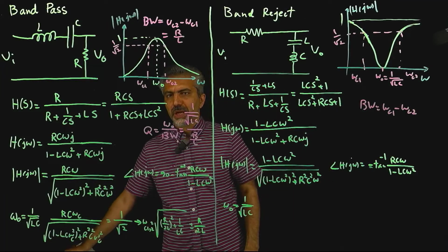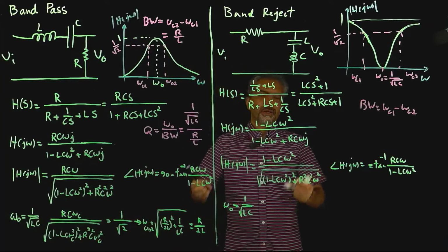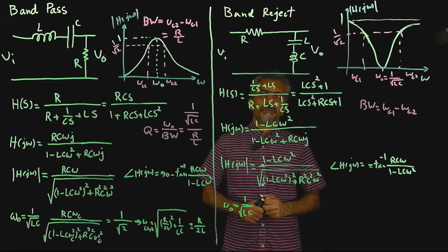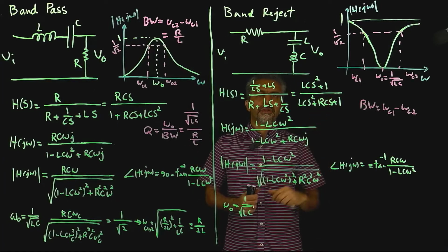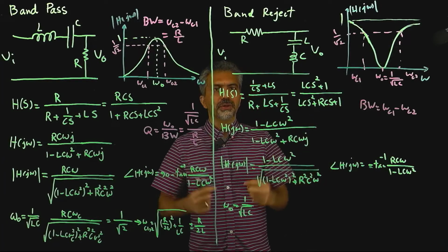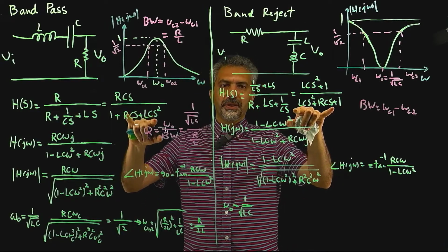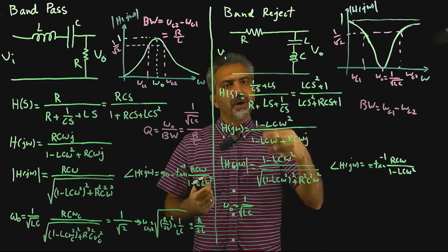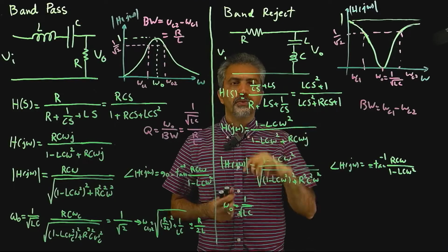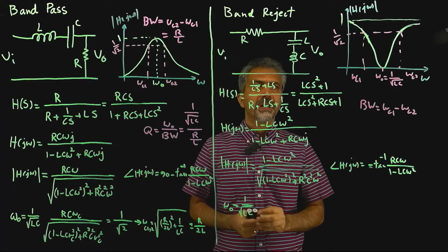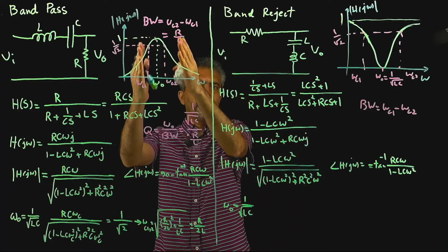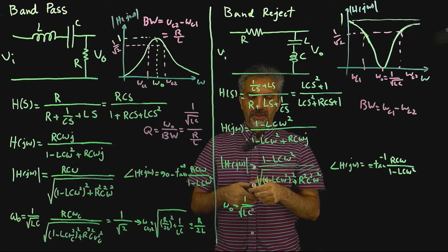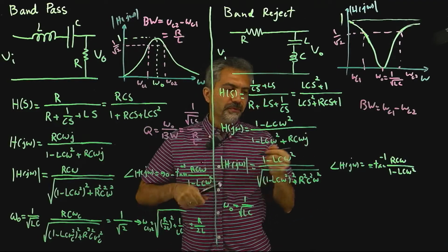And the same discussion that we had about the first order low pass and band pass filter, you can have that here too. You can have band pass and band reject filters that have higher orders, meaning that the denominator could be a function of s to higher powers, higher than 2, which is what these second order systems have. And if you do that, you're going to get sharper roll off, and the filter is going to get closer to what an ideal filter would have looked like.